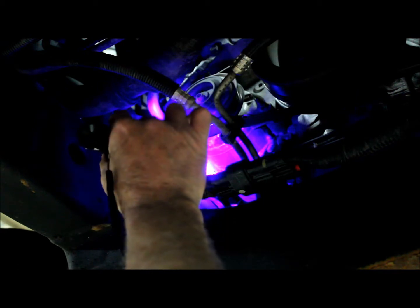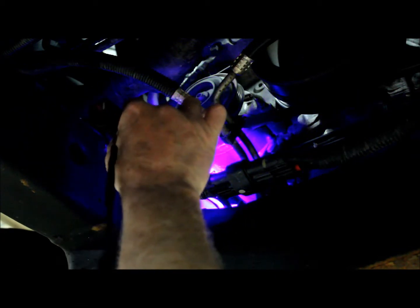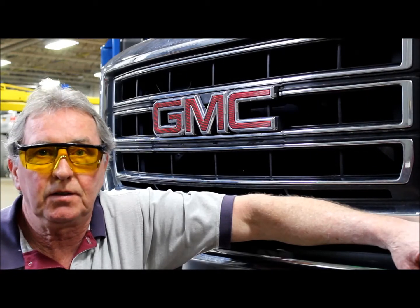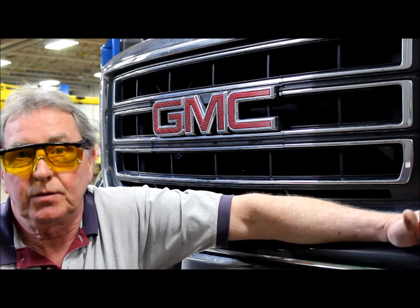One thing though that's important to note is the dye is water soluble, and so if the leak occurred a long time ago, it's quite possible that all of the dye got washed away, and the only way to find this may be to add more dye and run the system. So I don't see anything so far. This is on the bottom. I'll have to drop it down and take a look the same way on the top. Again, we'll check the condenser and the lines near the condenser to see if we can see anything here.